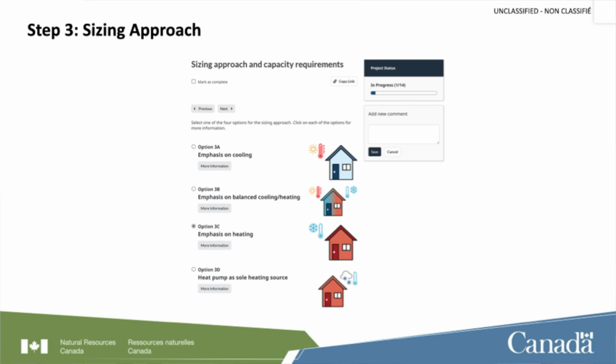And as I indicated in the first session, we can get into home designs with a program called Passive House, where we drive the heat loads in that home so low that you can run a heat pump as the sole heating source. You've got almost no heat loss happening from that house. Now, is that a cost-effective way to build? I don't believe so. I think you can get to net zero for almost the same price.